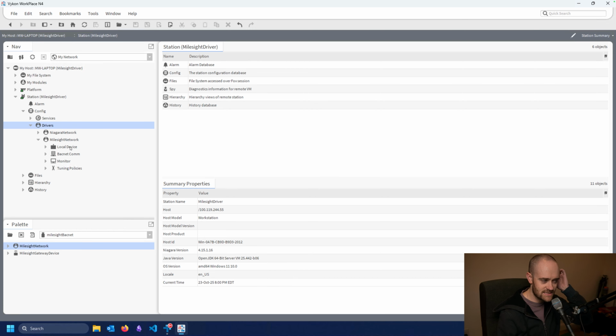This all looks very similar to what we were looking at with the BACnet driver itself, but you'll note there are 3 additional properties here at the bottom of this list. The first one is the URL. This is just going to be the IP address essentially for the gateway. So I know that is 10.10.1.206.